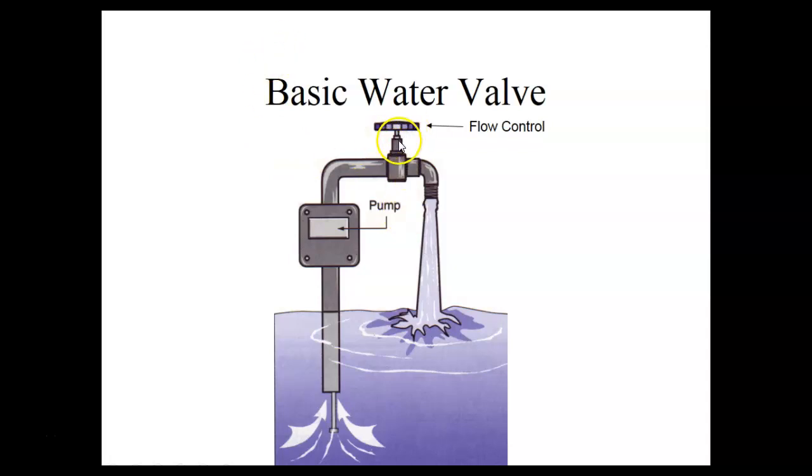It's an incline, actually a screw, that allows us to spread the force over distance, which means it takes less force to turn the handle than the force of the flow we're controlling. If you try to take your hand and stop the water flow, you're going to end up with a mess, right? We can't control the flow of the water with just our hand covering it, but we can precisely control the flow of the water with the valve.